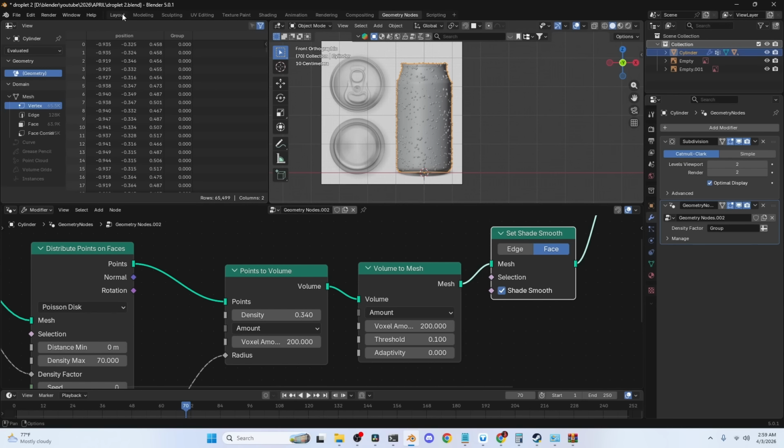I'm going back to the geometry node, select the scene again, then I'm going to click and drag the Bezier curve, put it here. Then Shift A, search for resample curve, connect the geometry to curve, then position, put here and here. At the resample curve, change count to the evaluated.